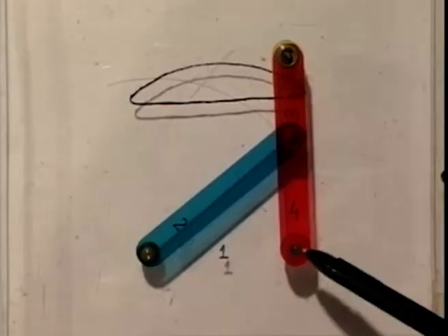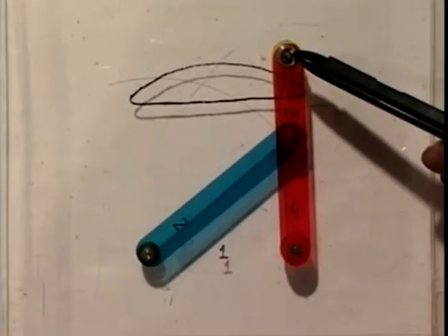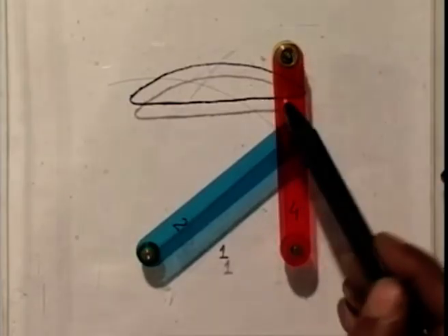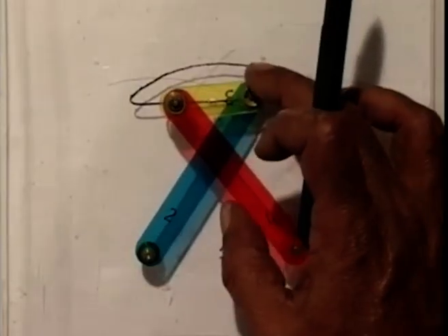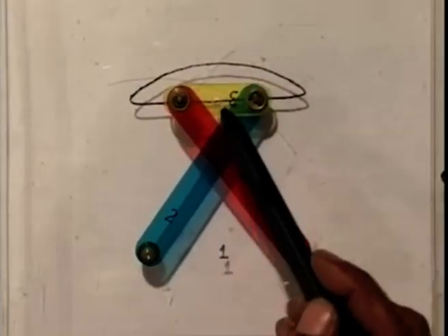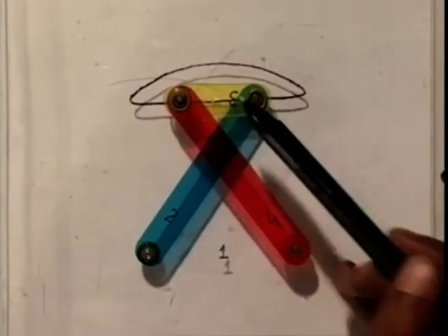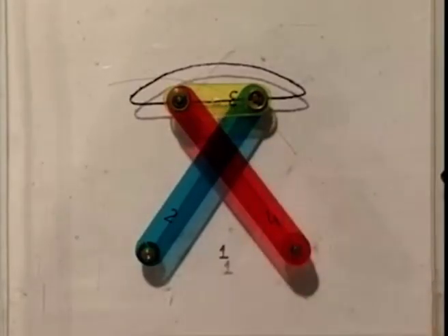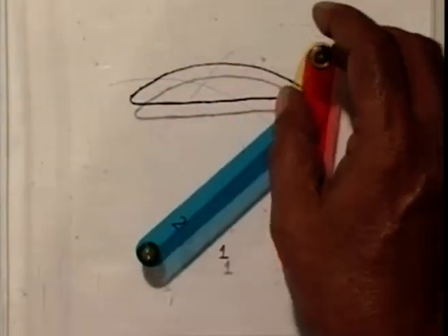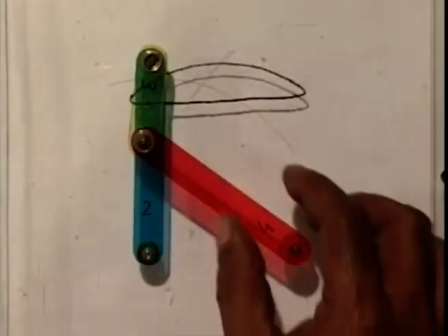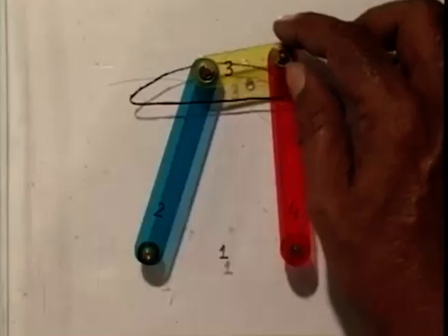This is again O4B and AB are vertical, and this is C2, the coupler point, and this is the symmetric configuration which we call C, O2, A, B, O4 with this point as C. So, this is the Chebyshev, which is again a double rocker, but as we see the rocking is all above the line of frame. So, it is a Grashofian double rocker, unlike the previous three.